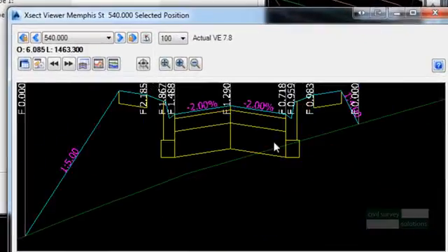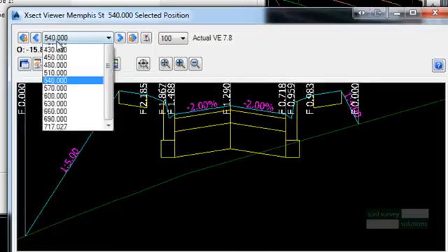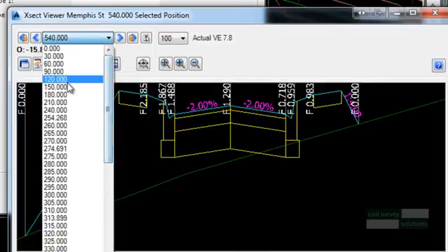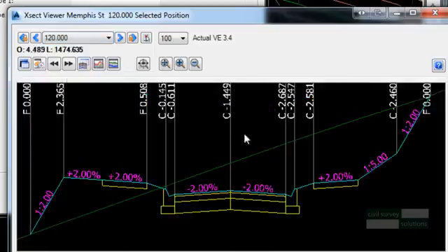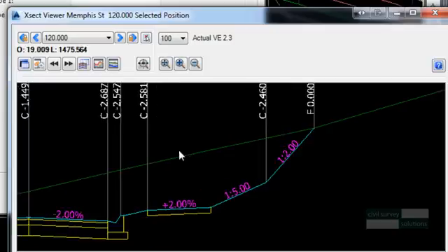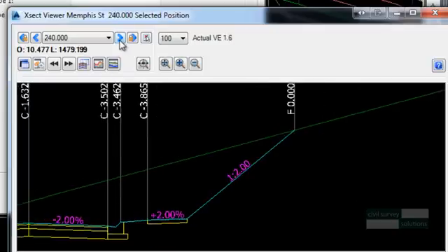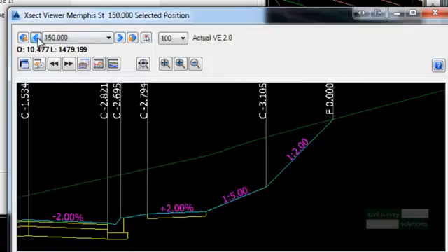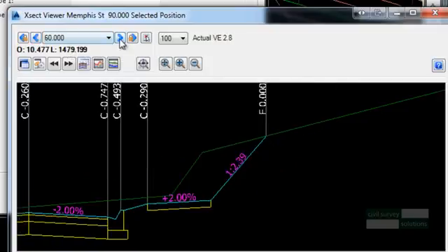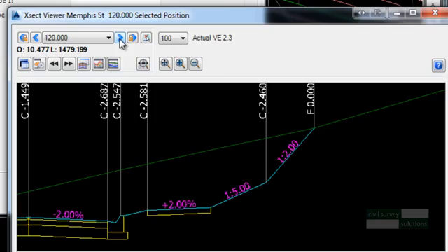The cross-sections between station 100 and 200 now display a two-section batter comprising of a 2% slope when in fill, or a 20% slope when in cut, followed by a 1 in 2 slope back to the sample surface. This would allow for a positive slope of the road reserve towards the road for drainage purposes.